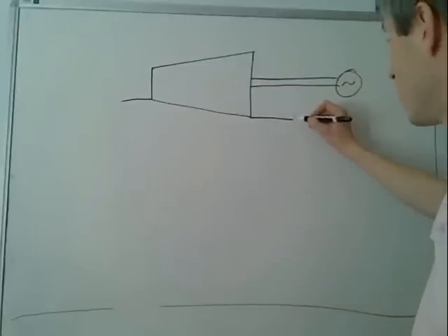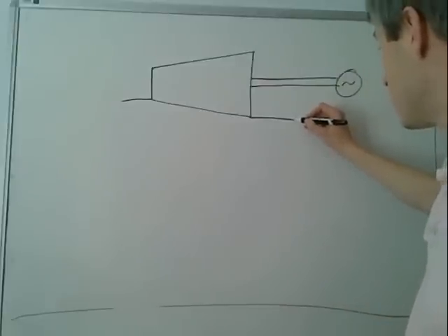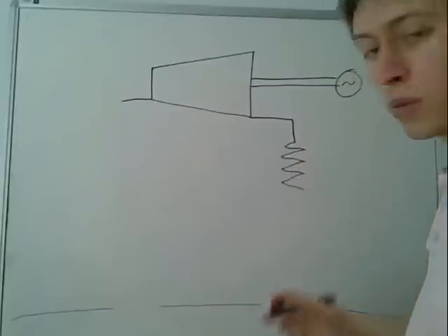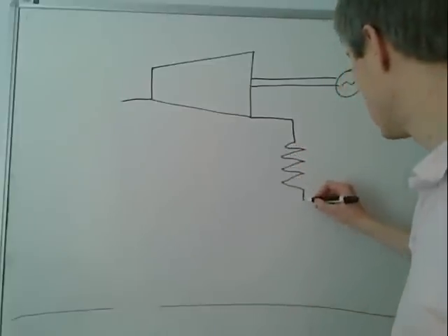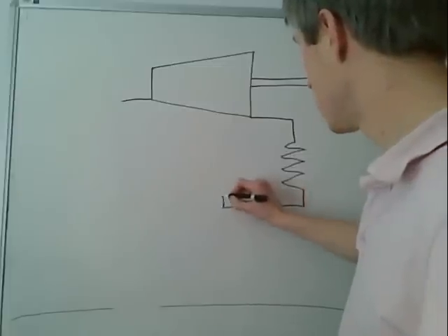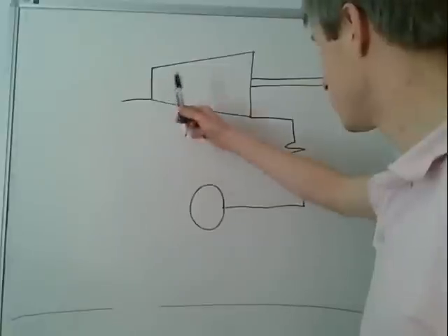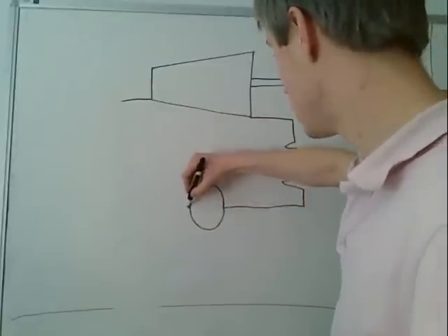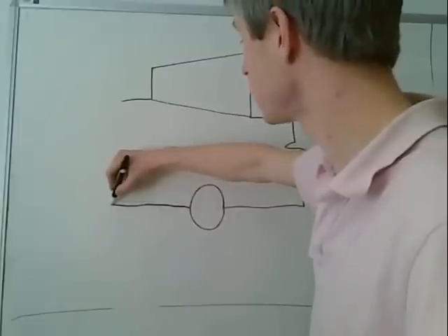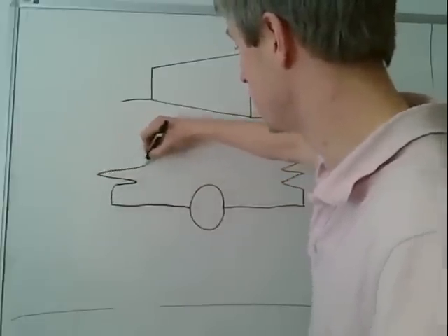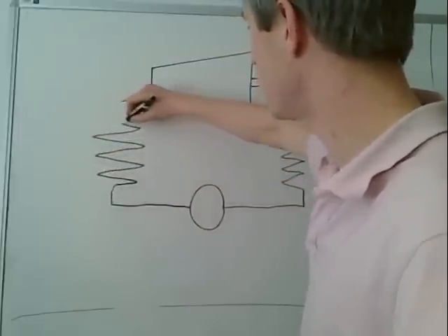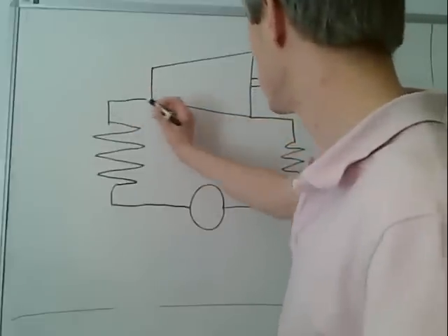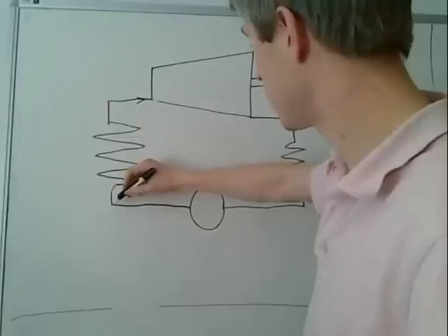This low pressure, colder steam comes out and goes into what we call a condenser, where it's turned back into water. This water goes into a pump to return it to the original pressure, but it's only pressurizing water now, so it costs less energy. And we put the water into a furnace or into a boiler, gets turned back into steam, and so we should maybe put an arrow on here so you know the direction of flow.